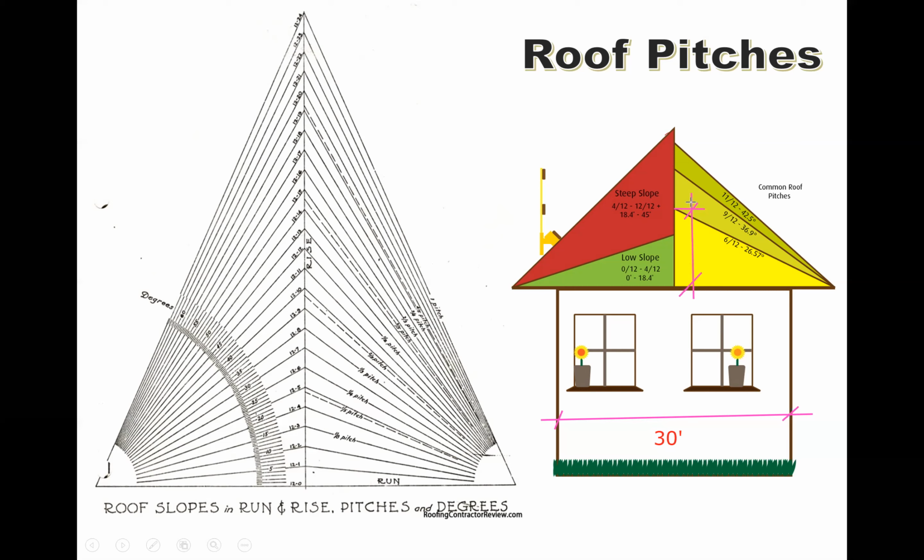So you can have an idea as to what the height of your roof is likely to be before you even construct it, because once you know the span, you can calculate what the height will be. So quarter pitch means a quarter of your span. And the span is the distance from the outside face of the wall to the outside face of the wall.